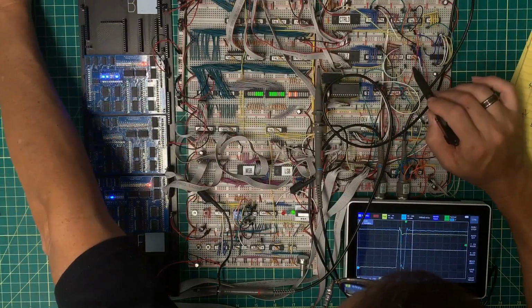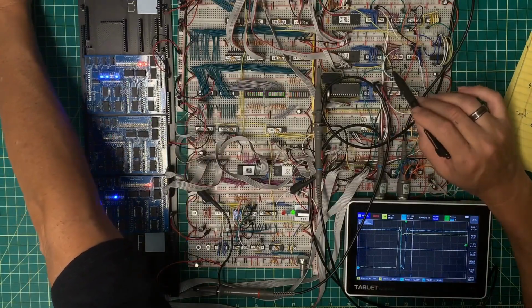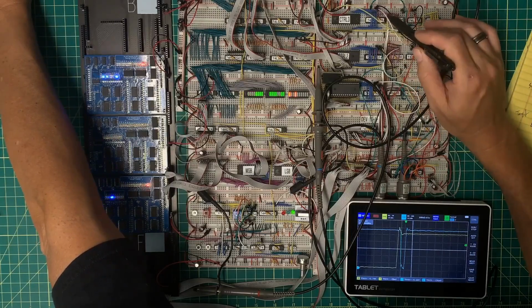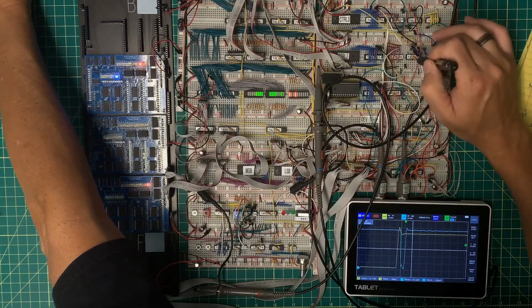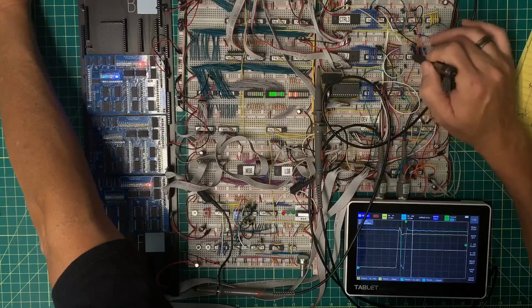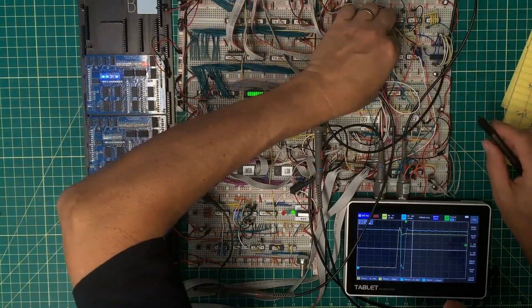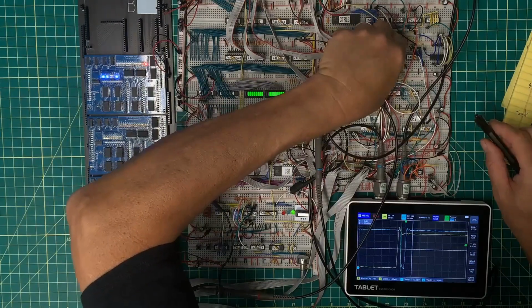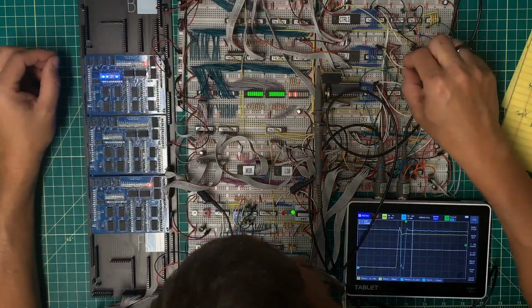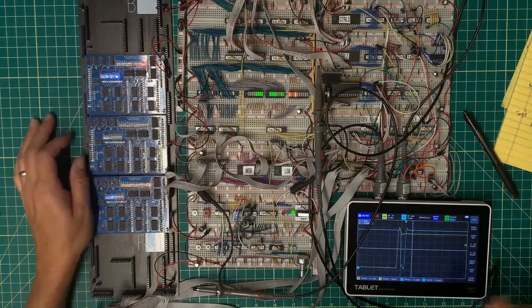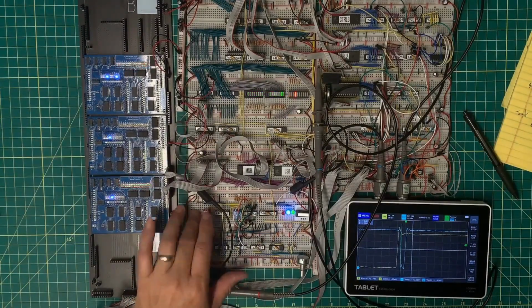Now, coming back here, I have these three for R2. Back to the overhead. These are coming off of control ROM 3. So up here, these are bits 4 and 3, which come down here on this clock. So these two need to be operating off of the same clock, and they are not. So this has to come out, and this then gets plugged in here.